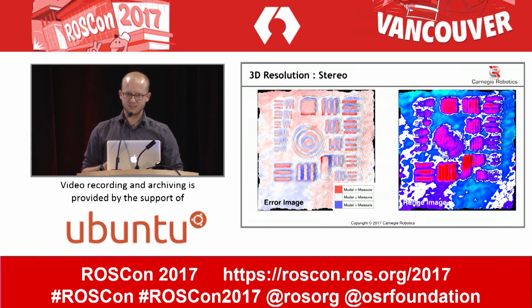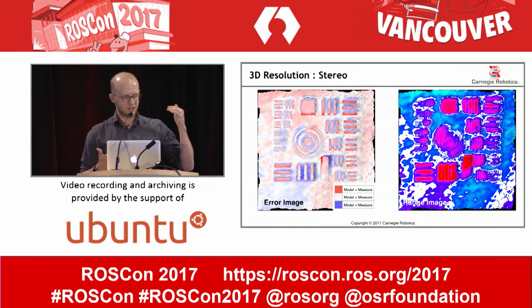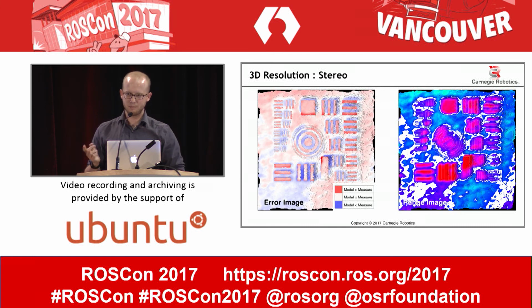In comparison, stereo is much higher resolution, so we're able to see the smaller targets, but because of the stereo matching process, we see very different performance in horizontal and vertical bars. The horizontal bars at the bottom left, you actually see the blue background between them. They're isolated and individual. And then the vertical bars actually web together because of the horizontal stereo matching process. You're searching left to right, and the accuracy of the camera in that direction is worse vertically. So you end up blending features, sort of smearing them horizontally, and that blends those vertical bars together.